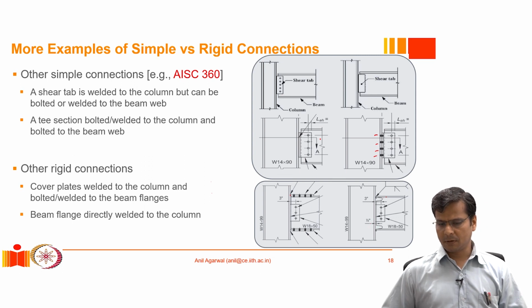Here also, in addition to that, you might notice that we require separate provision for resisting shear, which we did not require typically in an end plate connection. The reason for that is because these connections are very localized near the flanges, and the shear force demand at the flanges is very small, and plus we sometimes have to create these kind of cuts. These cuts are access cuts so that we can weld around this area comfortably.